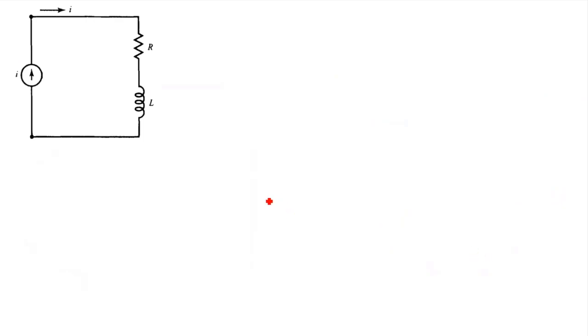Now if we find the equivalent circuit for this toroid, it will give me the resistance and inductance together, because this resistance will show the resistance of the coil around the toroid, right? And L is the inductance of the coil. So they both will be in series, and that is connected through a current source. So this will be the equivalent circuit for the toroid.